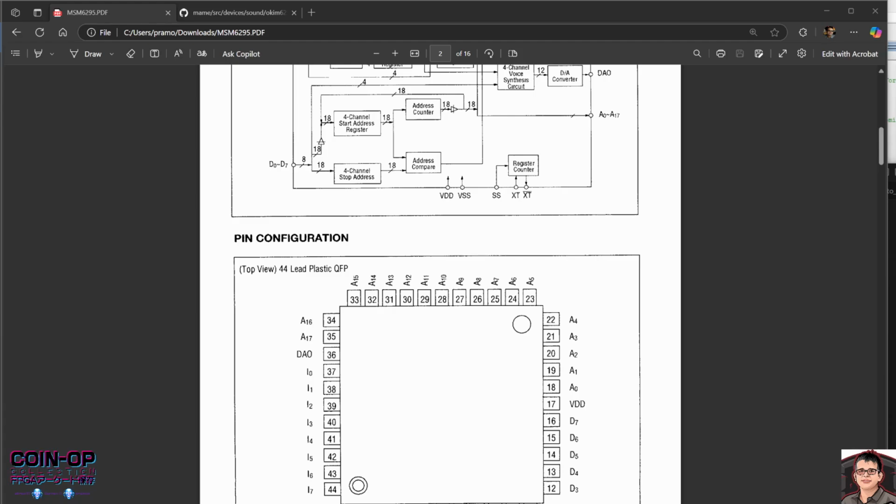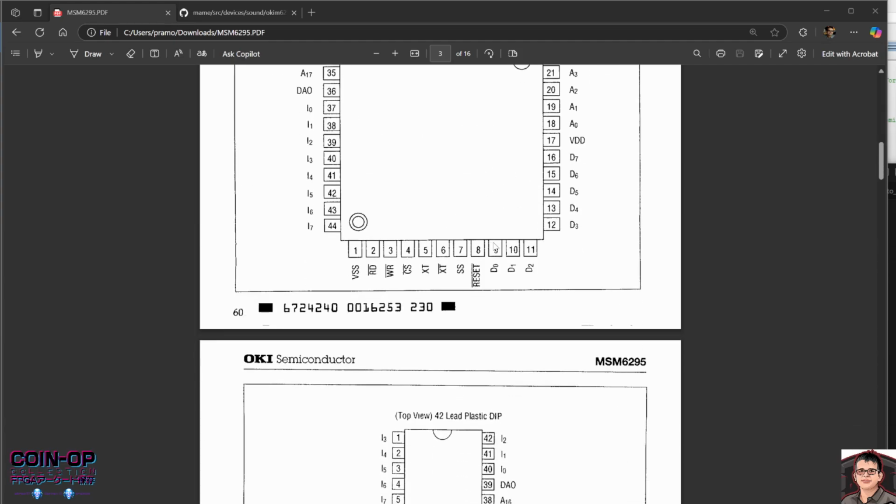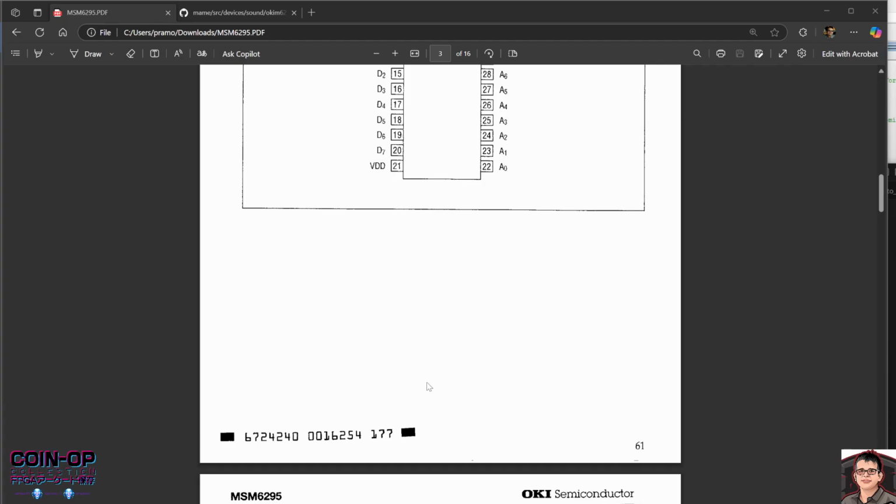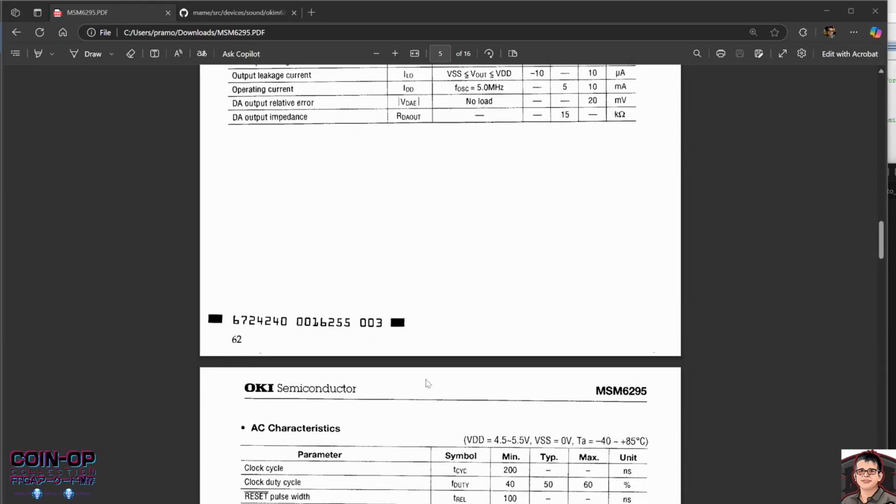And plus, memory is hyper fast on a PC versus doing it on an FPGA where resources are very scarce, right? And you have to worry about how you're using something and how long memory fetches take and whether they fit within the component time of your system, and all that stuff. So it's not really something we worry about in C versus FPGA. So that's the main distinction. Anyway, I would use this sort of information to tap the chip if I need to. Most of the time I don't, but sometimes you do.